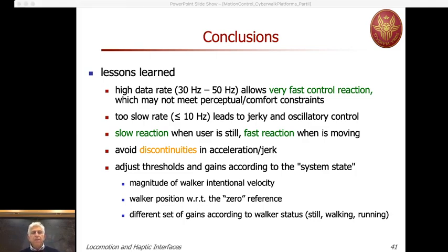What is the difference? The analogy in the case of a wheeled mobile robot comes from the fact that the robot is moving on a flat ground, and a fixed ground, I would say. In our case, we turn things on the other side. We have a fixed walker and a moving ground that has a non-holonomic constraint.